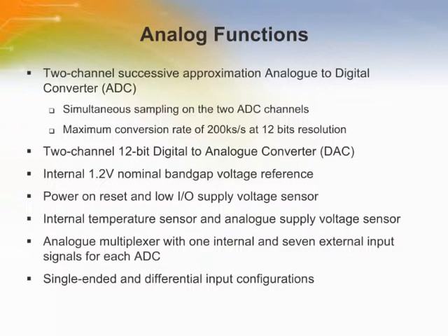The analog block also includes a power-on reset module which senses the analog supply voltage. The internal voltage reference circuit also generates a voltage linearly proportional to temperature. This is the internal signal which is available to the ADC as a temperature sensor input.